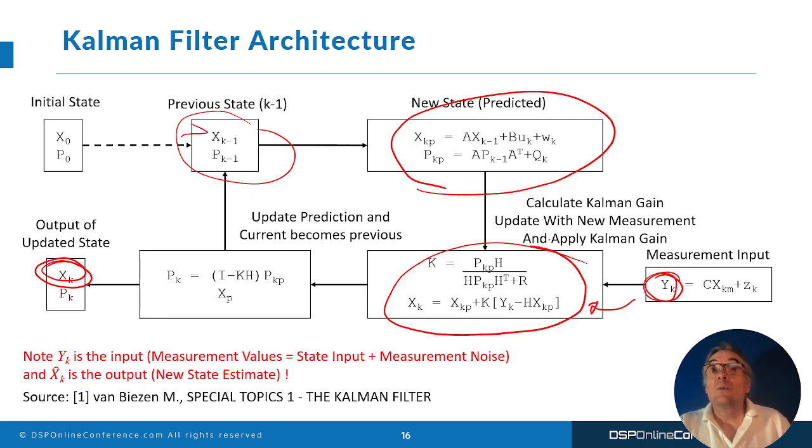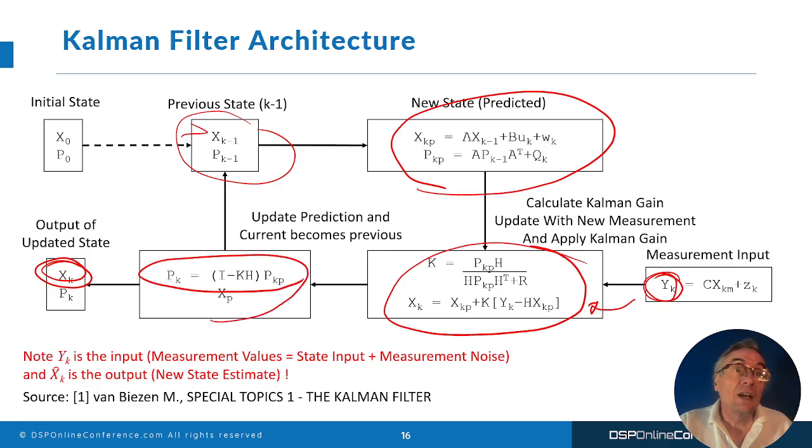Okay, so that's it. The only other equation we need to look at is this one here, where we're computing the process covariance matrix, or the estimation error. So we're just computing the error in our estimate, which we're going to save should it be needed further down the line in our process, but it will definitely be saved to go next time round the loop for the Kalman filter. Okay, so that's everything around the Kalman filter.